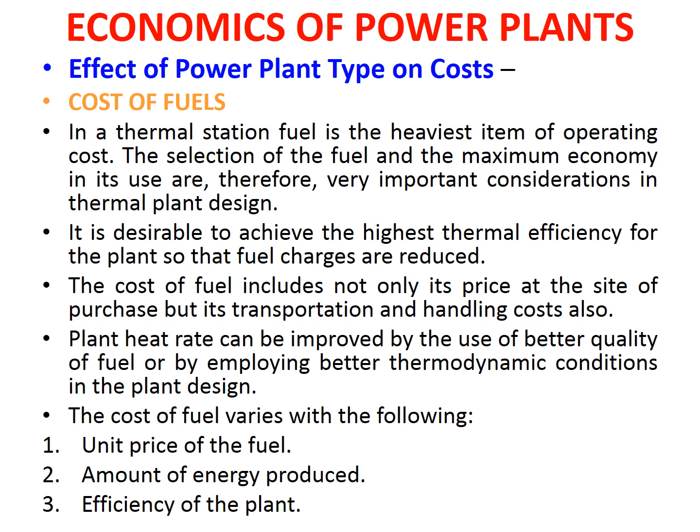The cost of fuel includes not only its price at the site, but the price of its purchase, and at the same time the price of transportation of fuel, and also the cost of handling of the fuel. Plant heat rate can be improved by the use of better quality of fuel or by employing better thermodynamic conditions in the plant design. So the cost of fuel varies with the following: unit price of fuel, amount of energy produced, and the efficiency of the plant.